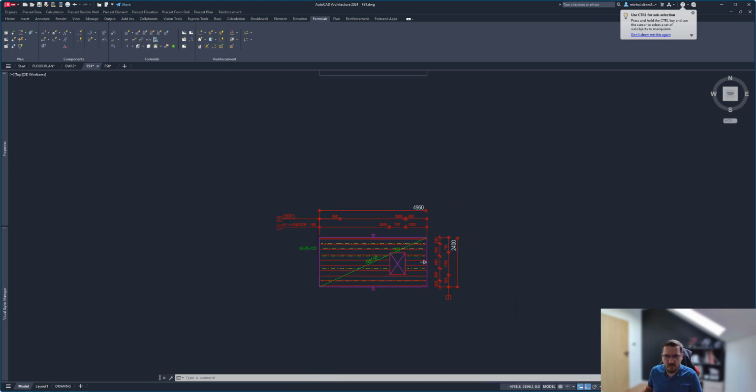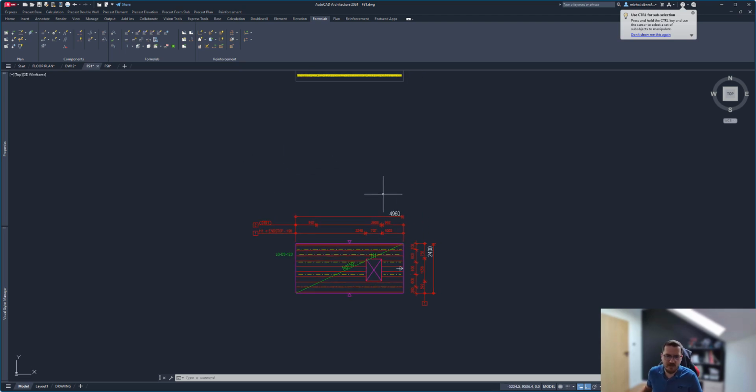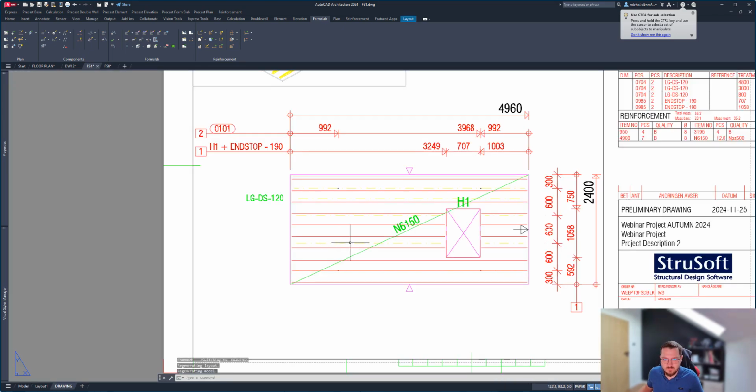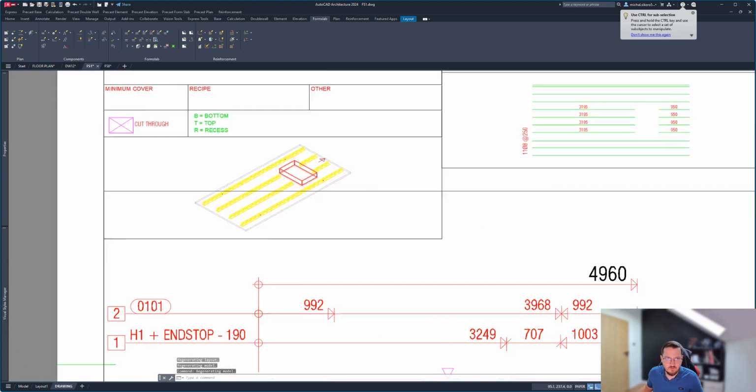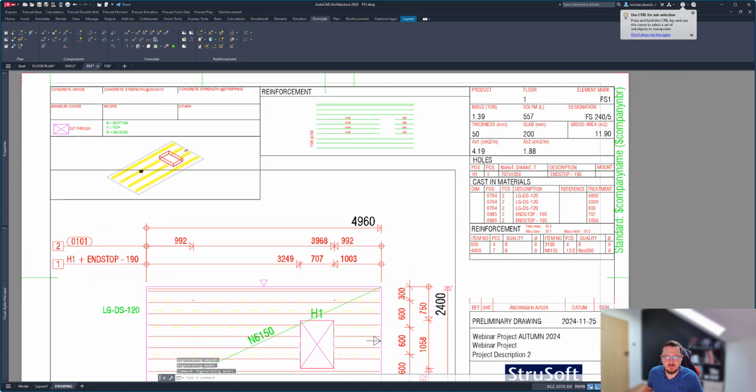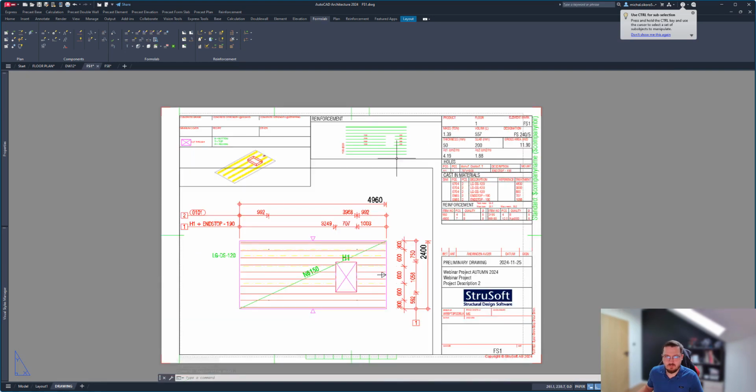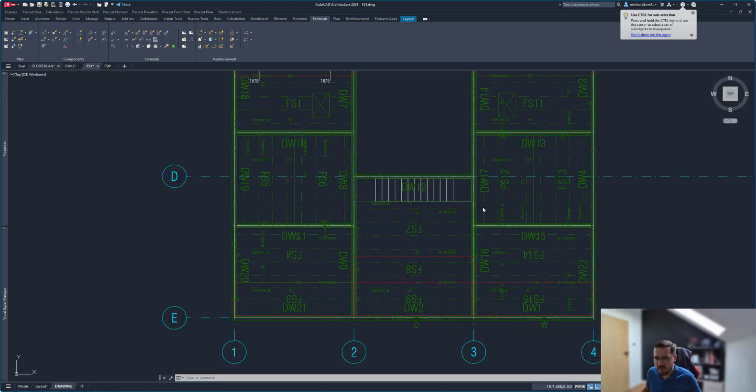So you can add girders here as well, edit those, save them to material takeoffs. Of course, for both double walls and form slabs, you can export the data format to Unitechnic and other machine formats, so they can be input into machines, and your meshes can be welded and bent as they are required. So again, go back to the drawing, and we have our reinforcement. If I refresh that girder, it would be there, and that's that reinforcement as well. Now back to the form plan or floor plan.